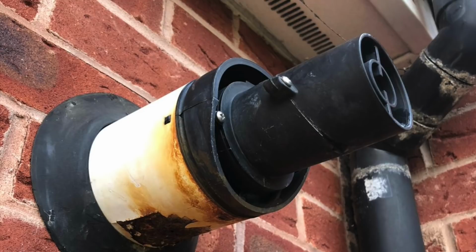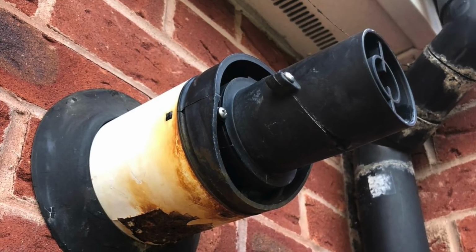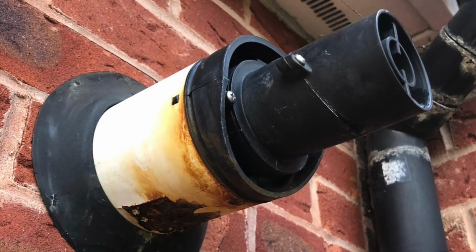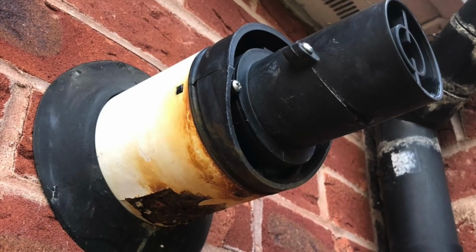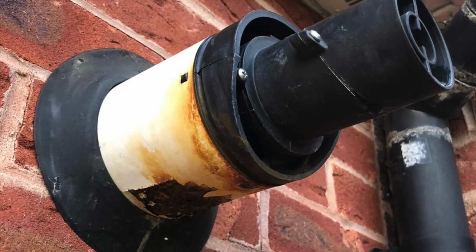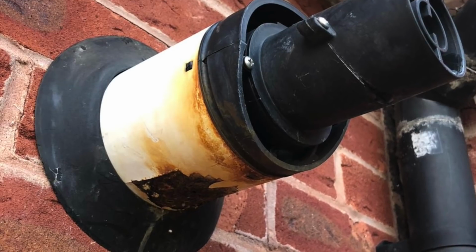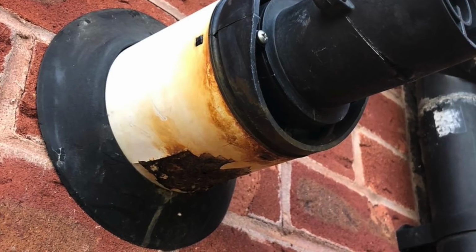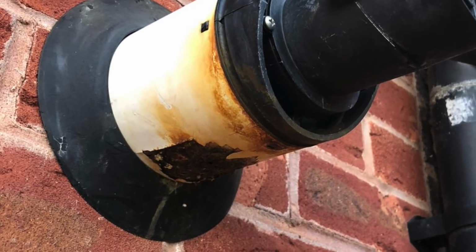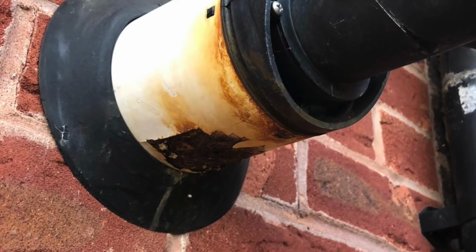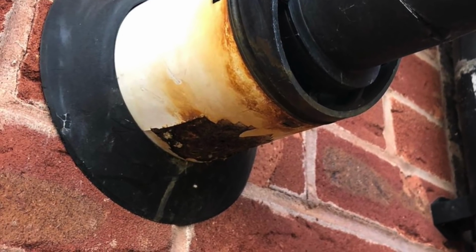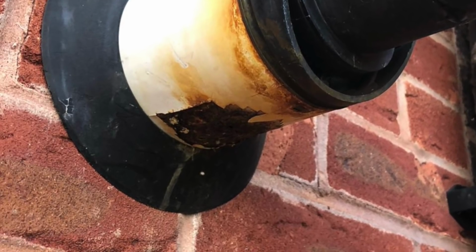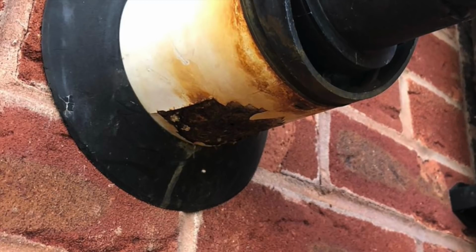So it's not just Ideal and Baxi flues which will rot away if you have them on the wrong angle and sticking out too far. As some of you will know, this is a Worcester flue. And you can see this flue has also corroded at the bottom because it's sticking out and it's falling back to the boiler. So what's happening is the rain's hitting the flue and then running back down to where the wall is, collecting where the wall is, and then just rotting away the flue. So there's no need to have a flue sticking out of the wall, whichever the manufacturer is.